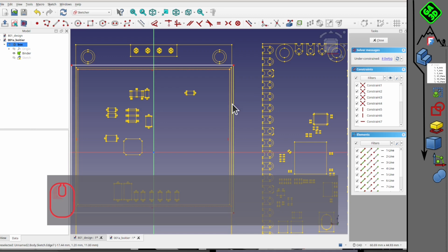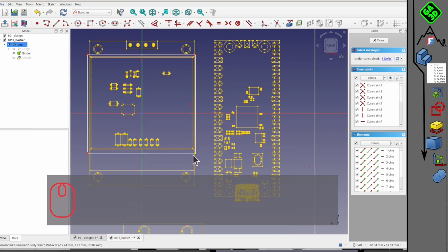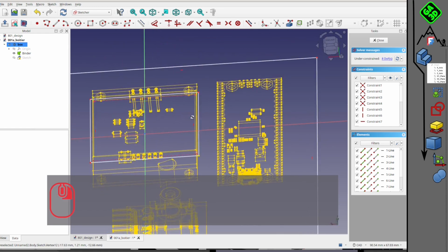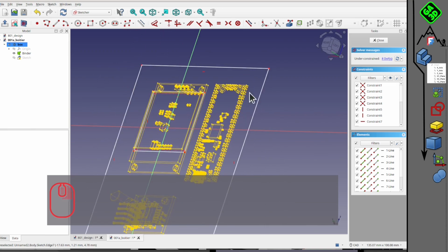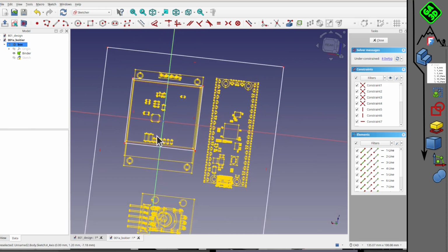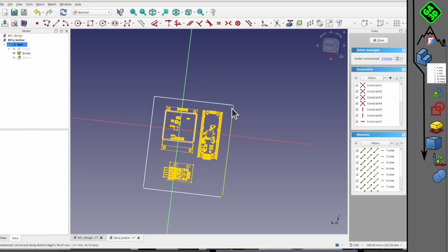Right now I'm going to do my sketch and then my extrusion. And here you see, it's right around, so I'm going to make a very thin 3mm thick case. That's enough, so there will be my screen. There, we validated and our shape is in there. It disappeared, we can make it reappear. It remained in wired mode.